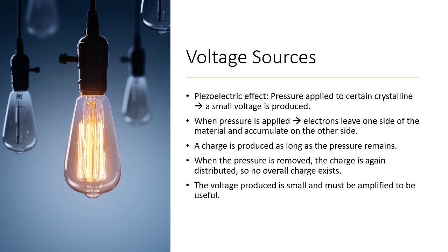When pressure is applied to certain crystalline materials such as quartz, tourmaline, Rochelle salts, or barium titanate, a small voltage is produced. This is referred to as the piezoelectric effect. Initially, negative and positive charges are distributed randomly throughout a piece of crystalline material, and no overall charge can be measured.